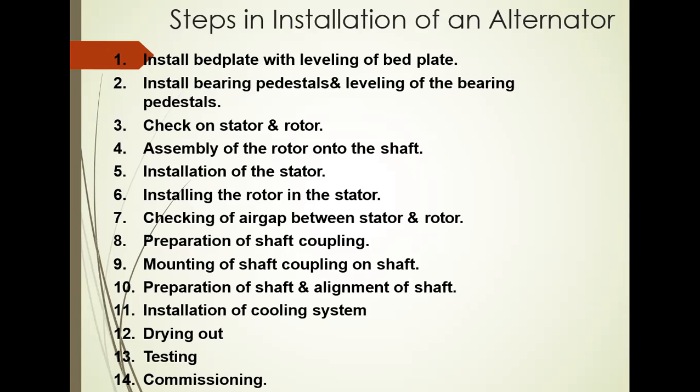After that, install bearing pedestals and level them. Then check the rotor and stator, whether everything is in good condition or not. Assembly of the rotor onto the shaft. Installation of the stator. Then installing the rotor in the stator. Checking of the air gap between stator and rotor.